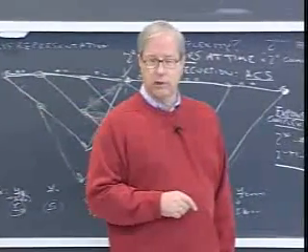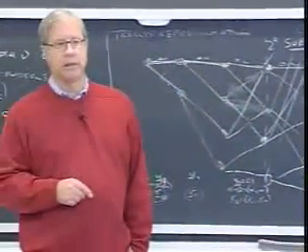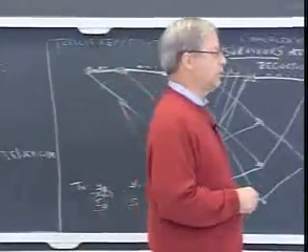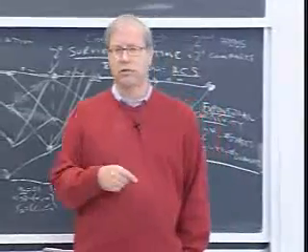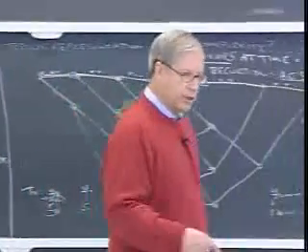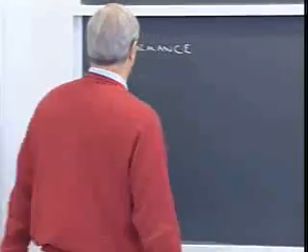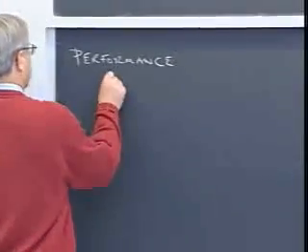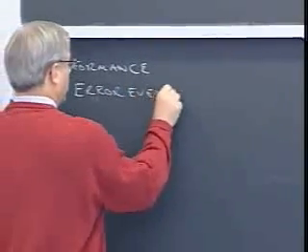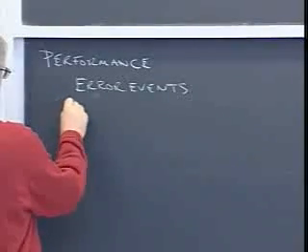And we can do exactly the same thing in the convolutional case. The convolutional case, again, is a linear code. That means it has the group property, a symmetry such that the distances from every possible code sequence to all other code sequences are going to be the same. It's just that we're talking on a long or possibly infinite sequence basis. And we need to be just a little bit more careful about what an error consists of. We need to talk about error events.